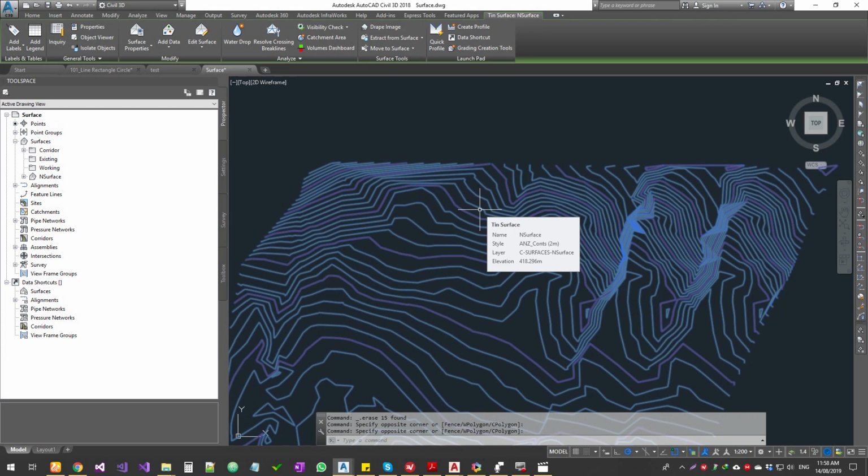Whereas with Civil 3D, we have two control lines. One is your alignment, another one is your profiles. The alignment controls how the pipe or road travels in a horizontal plane, and the profiles control the vertical plane. So they combine together to control the object.